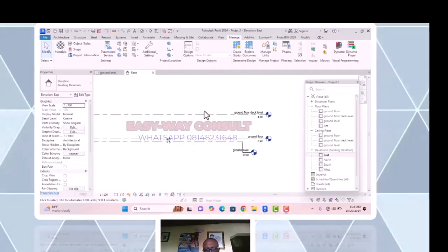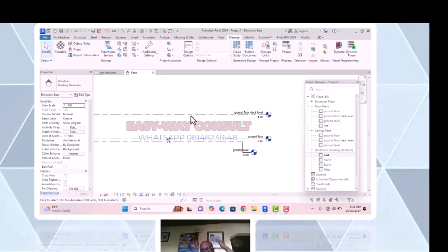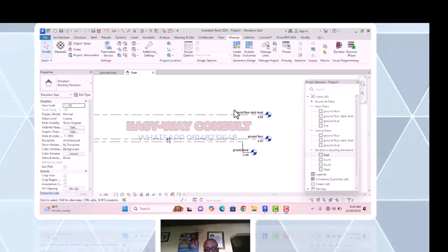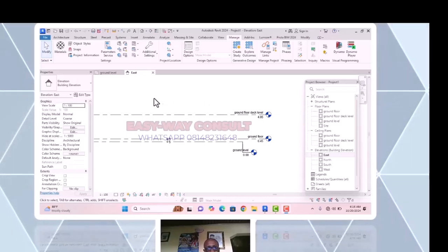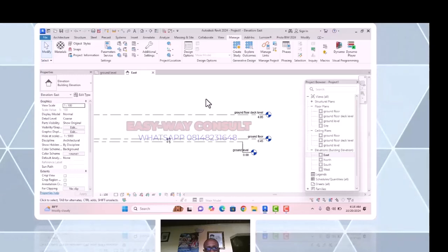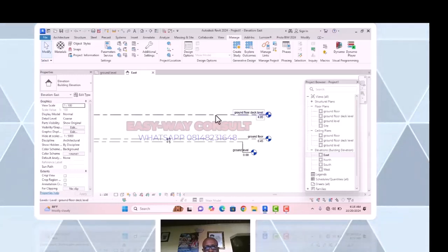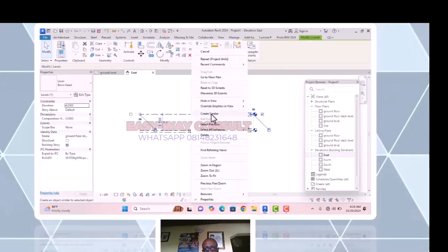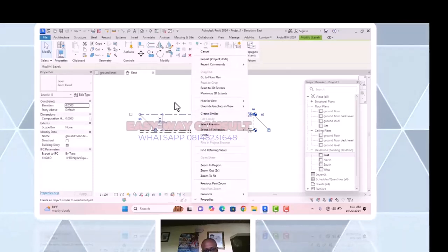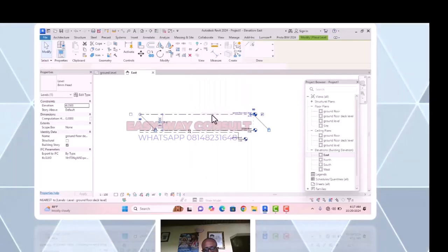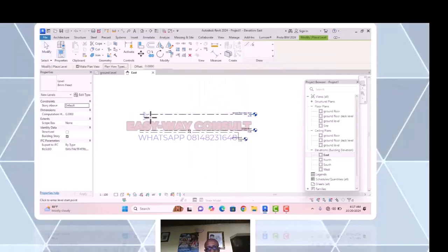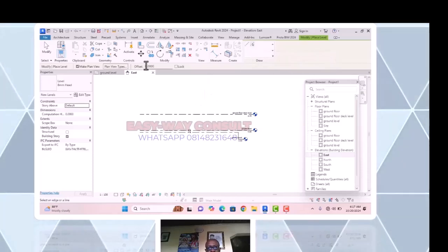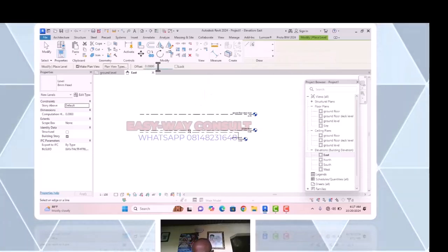Okay, so the next thing now is to get the slab, the first floor slab, before you get another level of the first floor. So I think what we do is to click on these two. You click on this, create similar again. You right click to get this create similar. You can pick or you can draw your line and take your measurement. But some people prefer to pick because picking will give you automatic thing you want.